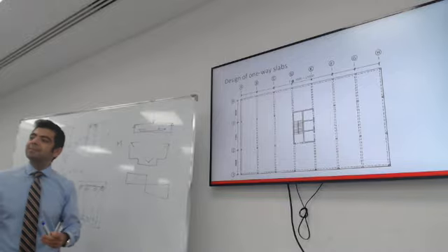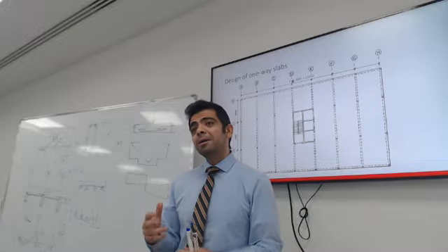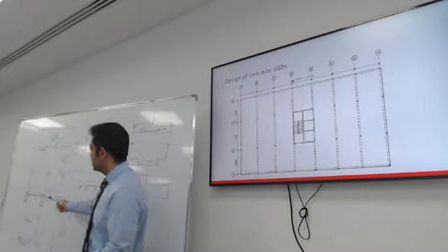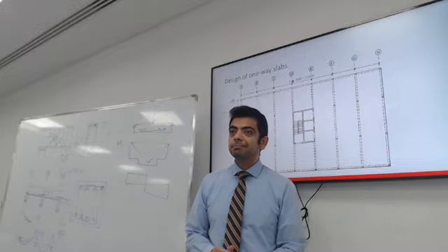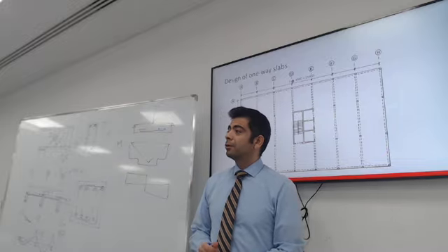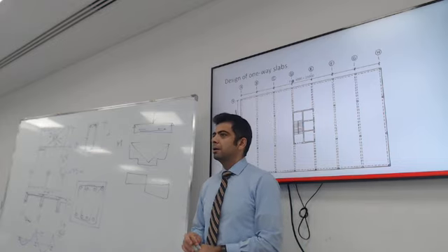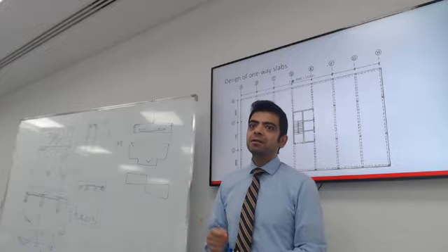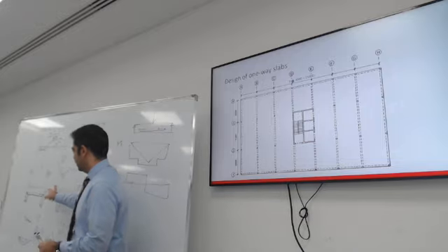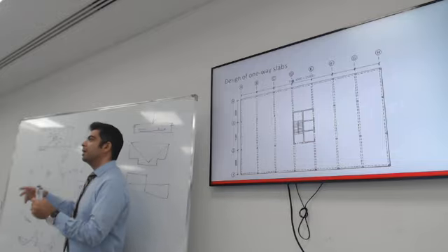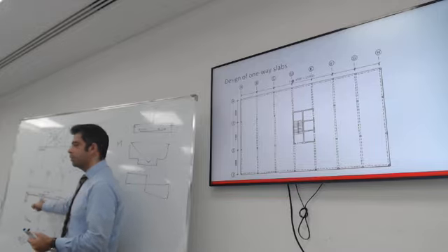So these are all detailing issues, but in terms of calculating the reinforcement, can someone guess how you calculate the number of bars at the top and bottom? Total area ratio, like you want to put minimum reinforcement? What is the main factor that will dictate the number of bars? The area, the load on this area. Right. So what are the straining actions? Is it the shear or is it bending that will mainly dictate the area of the bars?